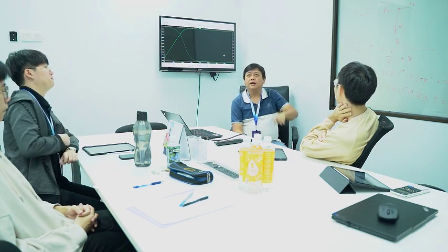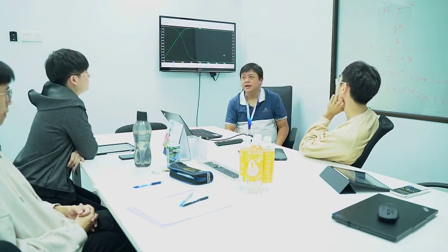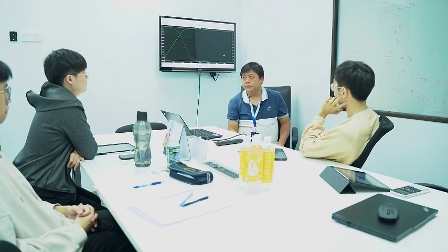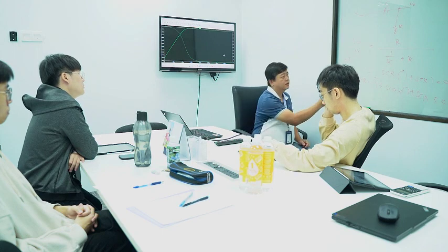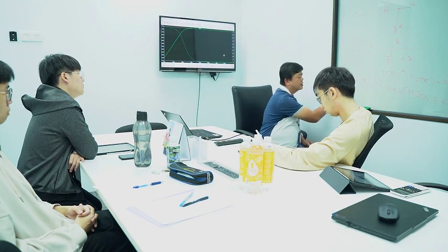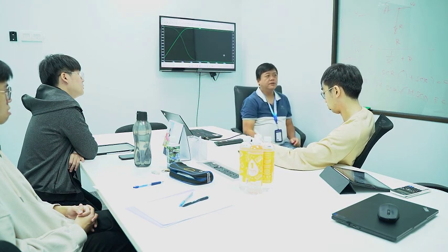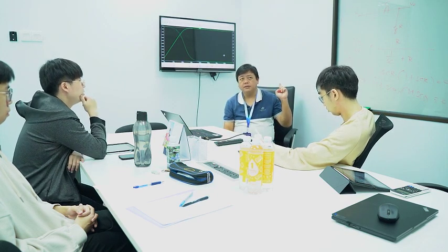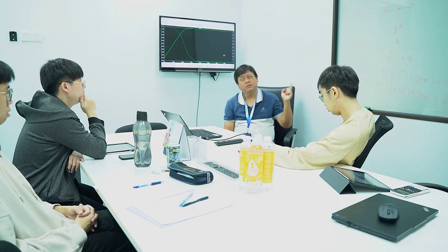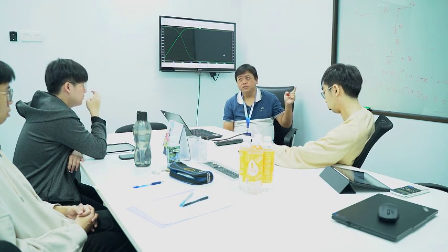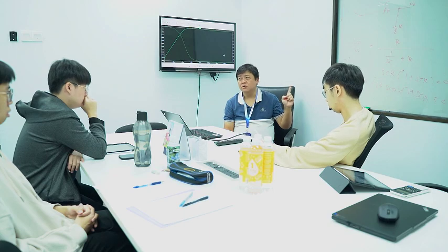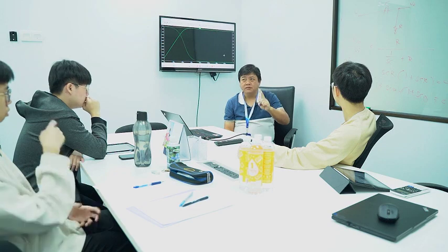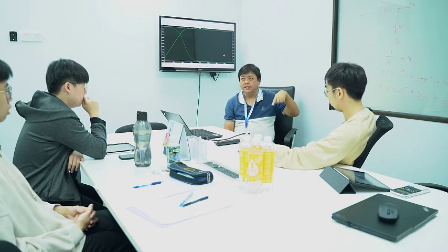Remember the phase of the PLL loop? We had an S squared, right? Remember the PLL curve? You start from negative 180, you still remember that, right? You start from negative 180 because of the double origin pole. You start from minus 180 straight away. If let's say it's a single S only, you start from minus 90 degrees.